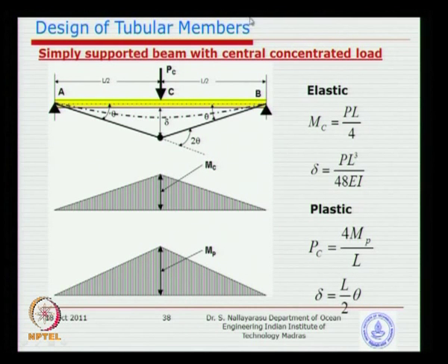That means, at that point of loading, the plastic hinge at the center will form, which basically means a substantial section of the beam has yielded for full depth. At that instant, the beam will start rotating about this point and start collapsing, which is called the collapse state. That is what we are interested in: when the beam will actually collapse, going from a linear stress-strain diagram to a rectangular stress-strain diagram. That point of time the load is called the collapse load.